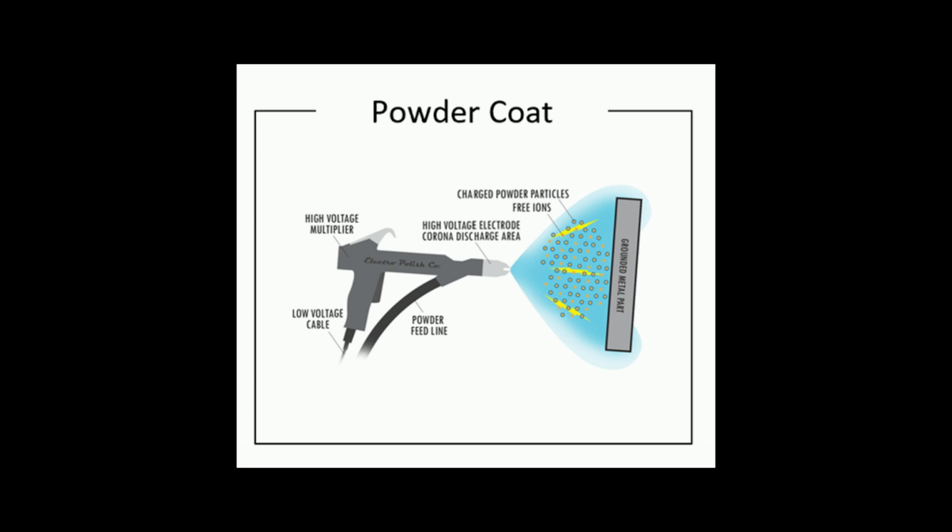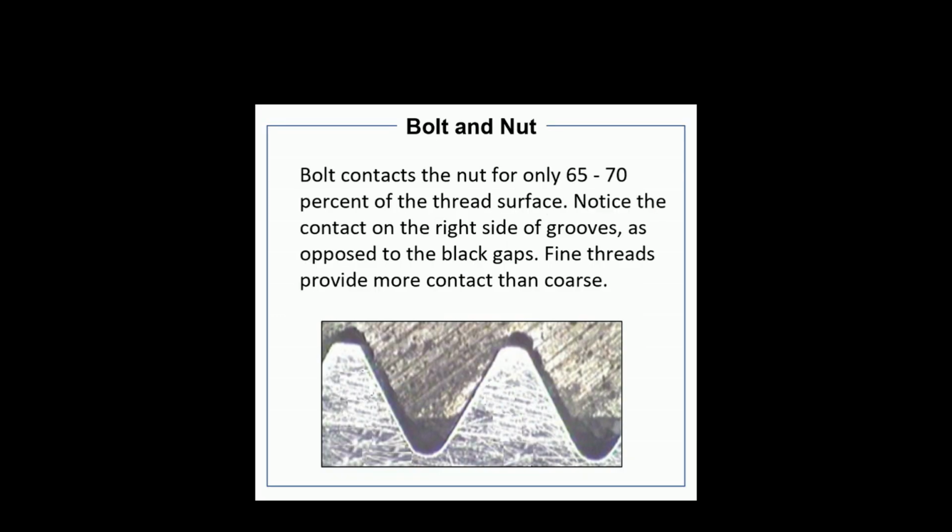Frame fasteners are typically bolt and nut style or huck bolts. Bolts are torqued using a wrench and are considered the most serviceable option. However, vibration during truck operation can cause nuts to loosen, leading to rail failures.